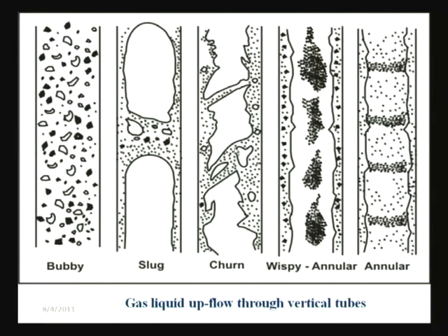Now, again you keep on increasing the flow rate. What happens? These bubbles become larger and larger. As they become larger and larger, they become unstable. And then finally a situation arises when these bubbles get sheared, they get broken up, and they keep on oscillating up and down in the flow passage, and they present a totally chaotic and random flow distribution, which is termed as the Churn flow pattern. Okay.